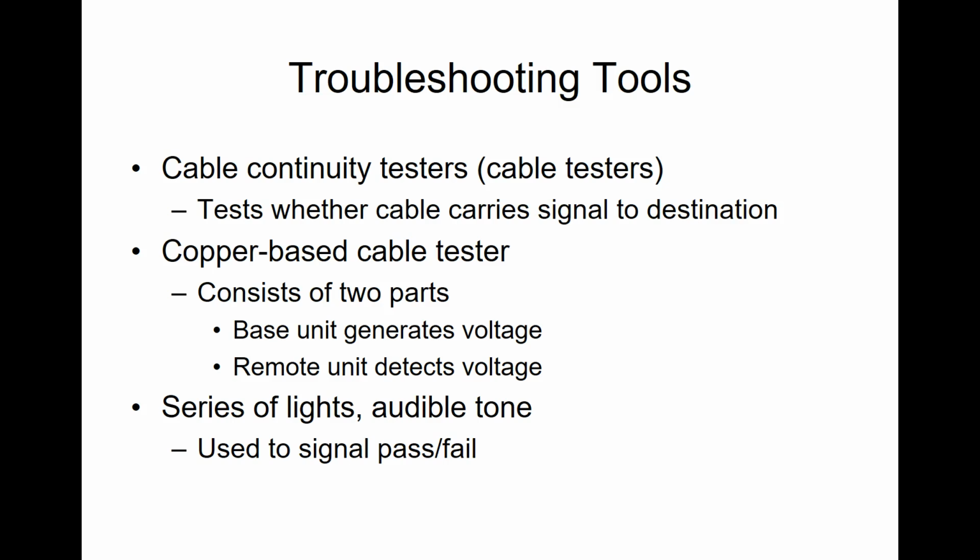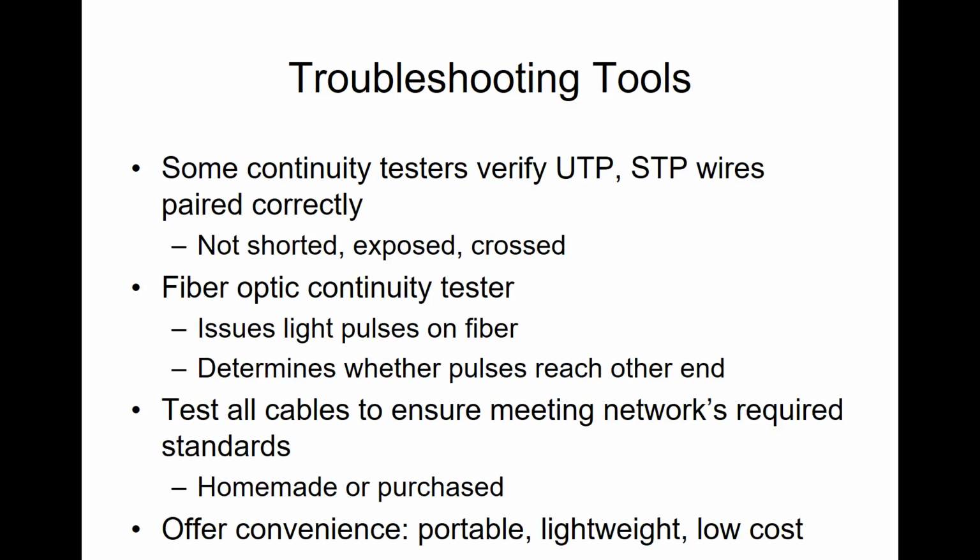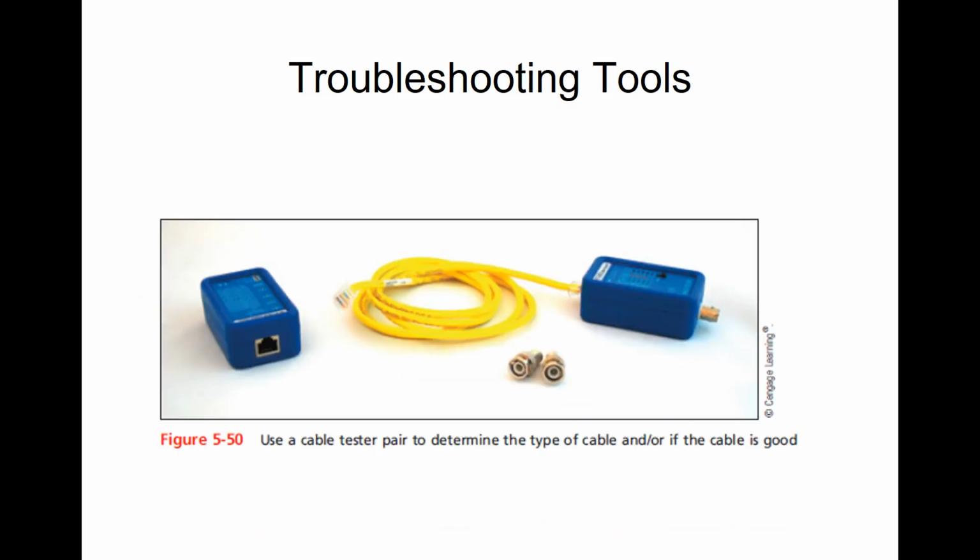So very important when we build something like this, we actually go through, like at that hospital, and you will certify each cable. Now, a certifier then can run $10,000 to actually do all of the testing for it, but we can get about 90% of the way then with just a quick pass. So you may see something and it looks like this. That is a really quick cable tester. And again, we've got some in the back that work very, very similarly. All it really does is check each line to see if it's connected right. It doesn't measure if it's connected well, but it does connect to see if it is connected at all.